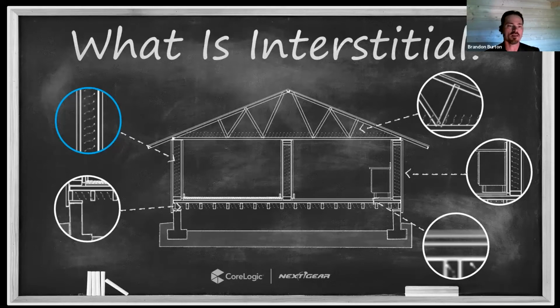And if that wet evaporating surface is in this interstitial space, or there's a chance that it is, then we need to access it. We need to inspect it. If it is wet, we need to impart mechanical systems or a mechanical drying system of some sort. And if we do that, then we need to monitor it, right? Anything that we're trying to dry or putting resources out to dry, there needs to be some data that helps us understand: are we effectively causing change? Are we affecting moisture within that environment?